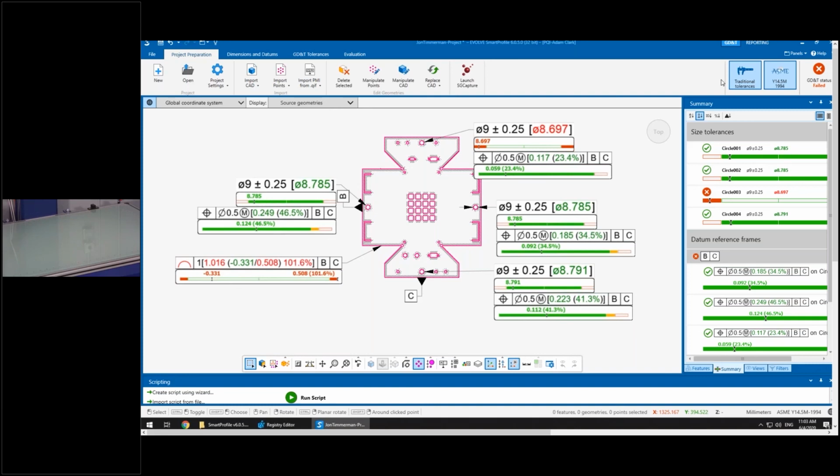Now I'll say, because we're going to be measuring everything at different times here, I wouldn't expect us to be able to nail it within a couple tenths. Well, maybe we can get a couple tenths, but I'd say hopefully we can nail it within a thou of the number you were hoping for, and then we can go in from there.